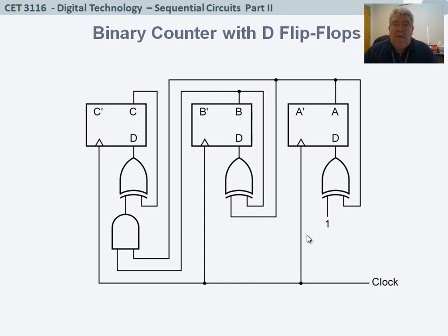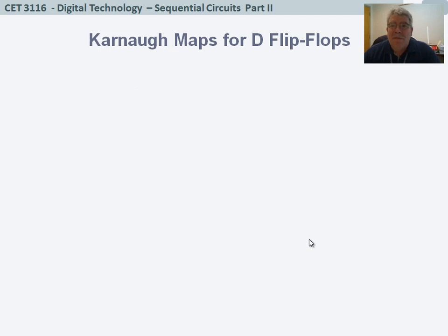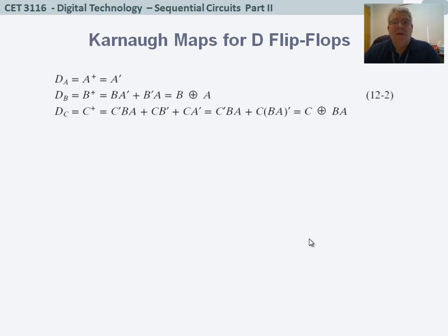Now, if you want to check that, suppose our procedure is to follow the state table and then think in terms of flip-flops. We can deduce the equations for D. D A is exactly whatever A next is going to be. And for that purpose, remember that we are interested in A not, right?